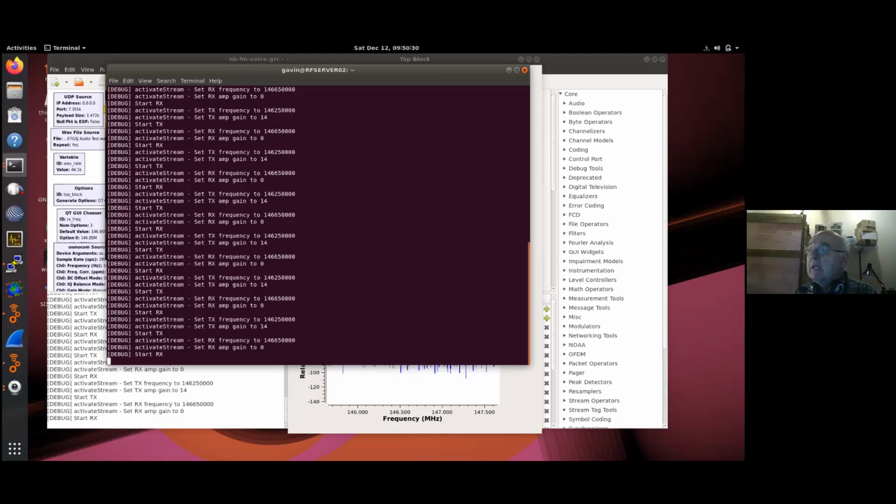But I had to go outside the recommended practice on that, or implement some other method. I looked at messages. I looked at having a button you push in the flow graph and so on. But the thing that actually clinched it is that the HackRF had this capability. The Osmocom HackRF block that I found, even though it didn't work, had that switch already built in. So I just expanded on that. That was why I chose this. But yeah, you might be able to do a better job using a Qt GUI push button or something like that, or message streams. But you're still needing to switch streams on and off.